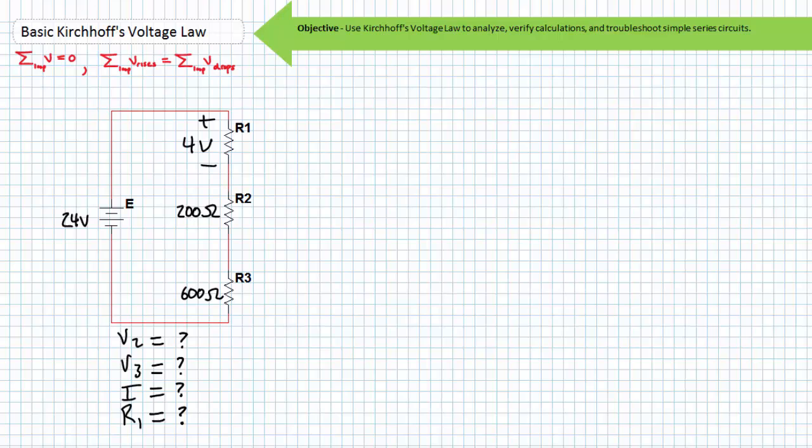Those with only a superficial understanding of series circuits are immediately repelled by the first obstacle they encounter, because they are often reliant upon calculating the total resistance, being the summation of R1, R2, and R3, and then using this value to calculate source current, being the source voltage divided by total resistance. With an unknown R1 value, one cannot solve for total resistance. Without total resistance, one cannot solve for source current. One can, however, use Kirchhoff's voltage law to determine the voltage drop across the remaining two resistors.